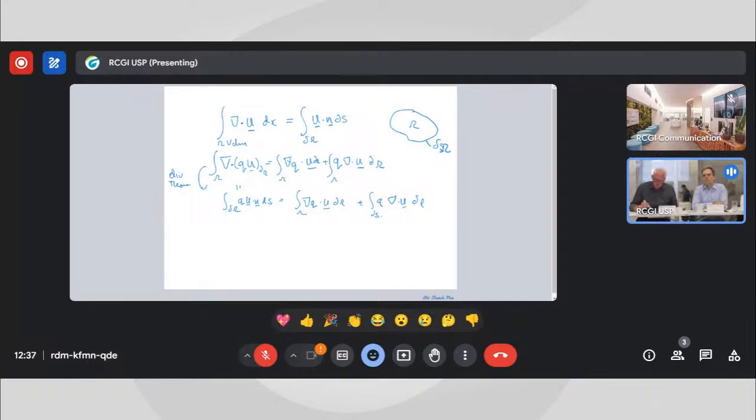So by applying the divergence theorem, I want to rewrite any of my terms, that's the gradient of q dot the vector integrated over the solution domain, as equal to minus this term, if I've taken it to the other side of the equation, q divergence of u hat d omega, plus, now that I've applied the divergence theorem, something integrated over the boundary of that control volume.